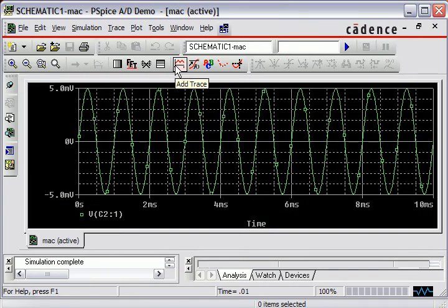As you can see, we're using basically our amplifier, and the resistor is a voltage divider, and right in between our voltage is 5 millivolts, which is half of our input voltage. So it means that our input impedance is basically equal to the impedance of our resistor, which is 21.2K.